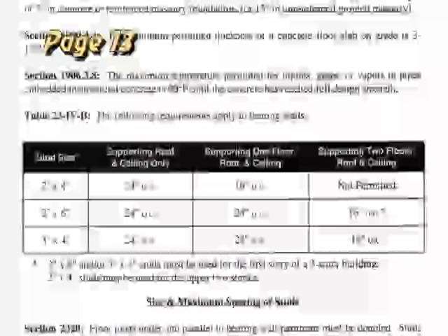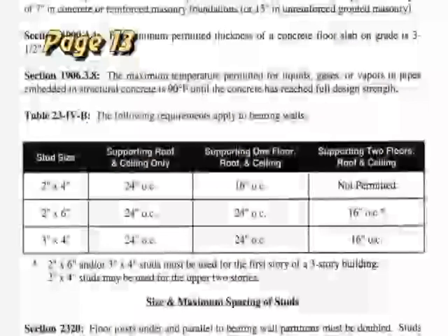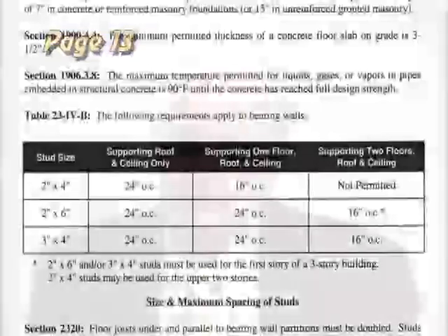Let's look at table 23, Roman numeral 4b. What that table says simply is that as you get more and more weight on a wall, that wall needs to have the studs put in more frequently with smaller spacing, for example, going from 24 inch to 16 inch, and possibly you might have to beef up that stud, going from a 2x4 stud to a 2x6 stud. Look at that table, understand what it says. You'll most likely see a question or two on the exam from that table.